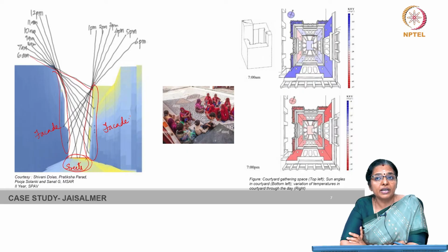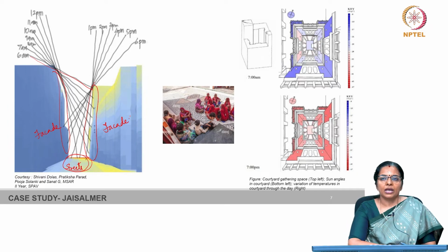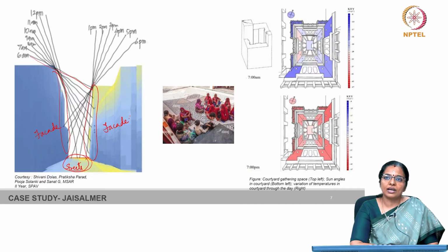Controlling solar penetration through orientation and projections is crucial in summer. It is optimal for a major east-west street orientation to have solar exposure on the street from 9 am to 2 pm, with a corresponding solar altitude ranging from 54 to 86 degrees. Small projections can effectively provide shade during this period.